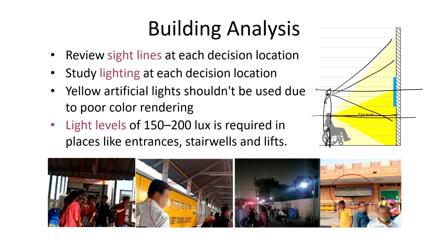consider a decision location where passengers need to choose between different gates. It's crucial to ensure that the directional signage guiding them to each gate remains visible within their sight line without any obstacles, objects or structures. If there is an obstacle blocking this view, such as columns or a display, the signage should be strategically located above head height to maintain visibility and guide users effectively.